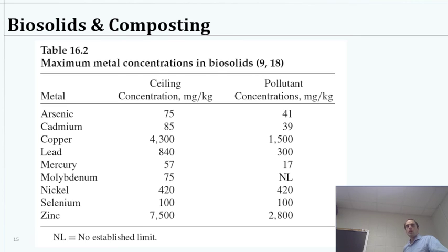Okay, so there's a maximum metal concentration in biosolids. This is actually a sub-program now of the NPDES system. A lot of states have a biosolids permitting process underneath that. So NPDES is primarily surface water discharge, but we needed some regulatory framework for biosolids, which is closely related to surface water discharge, but it's definitely not water. So it's just kind of, I guess, an odd placement, but that's how it went.